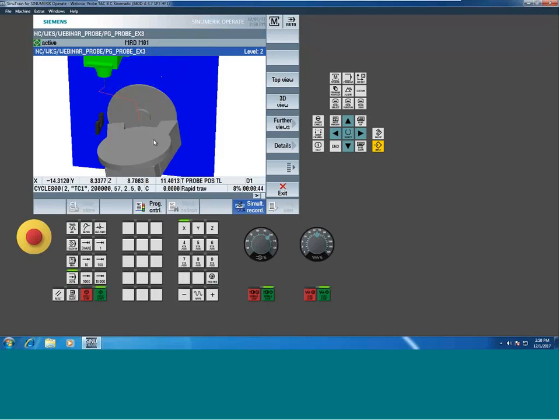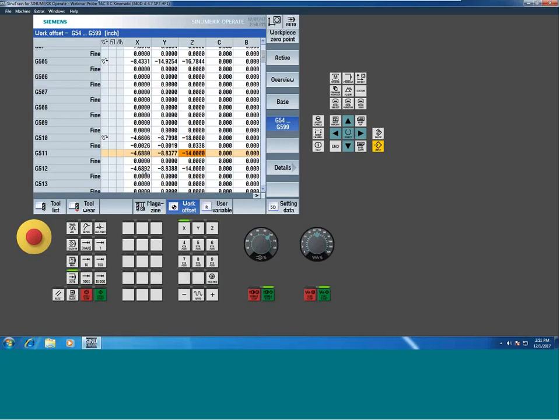And then we're going to continue, and we're going to do the measurement around the 2 sides. So around the first side, around the second side. That writes to 512. So then it's going to update right here. So I can zero these out, and we can rerun it. So she's coming around measuring the top. You see I got some slight change. The Z is not going to change, mind you, because I didn't take any measurements of Z. I'm just doing X and Y.